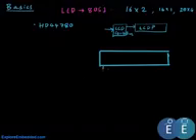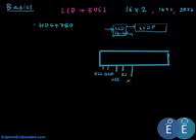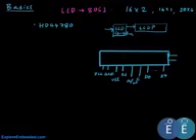There would be 2 pins for the power, which are VCC and ground, and then a contrast pin, VEE, and the register select, read write, and enable pins. Apart from that, you will have data bus D0 to D7, and you'll also have an LED inside which lights up the back panel, with an anode pin and a cathode pin for that.